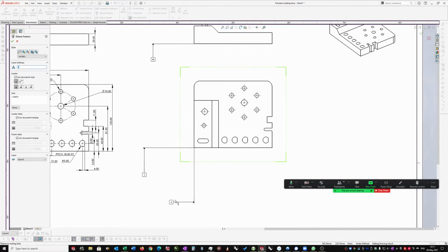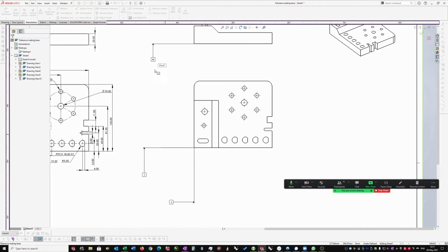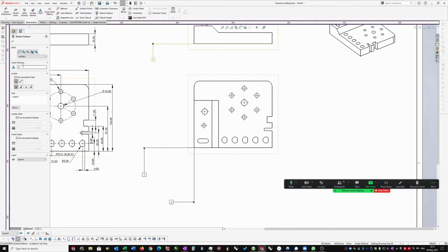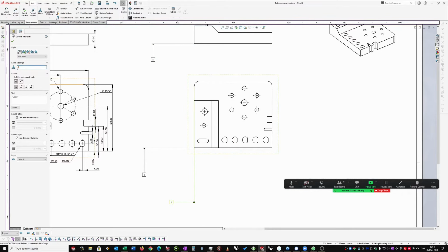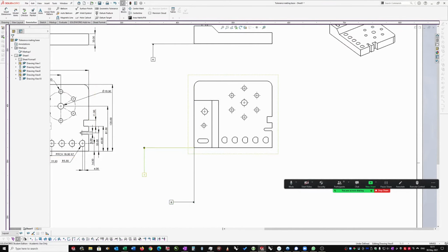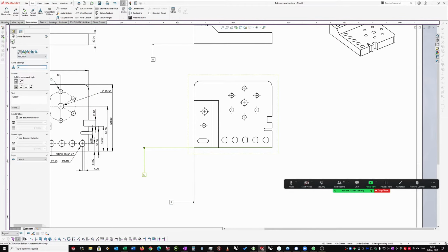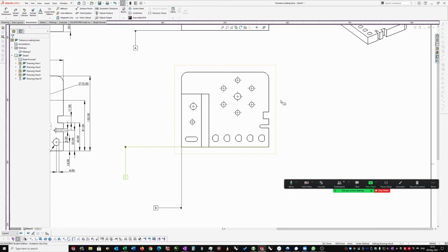And it's just renaming them as HIJ because I've used up the other letters already. So I can always go into this datum and I can rename it on the left hand side A. And that one I can go to make it B. And this one C. So once you've got your datums established, then you've got the basis for doing all of your dimensioning.